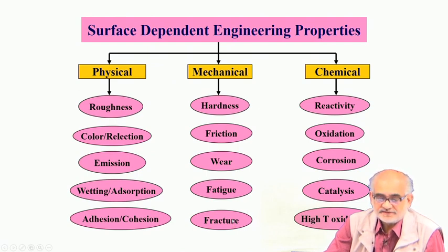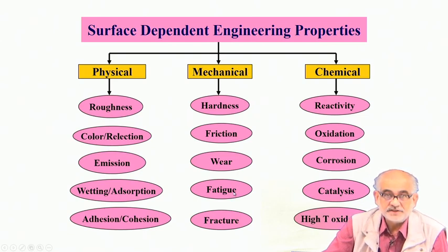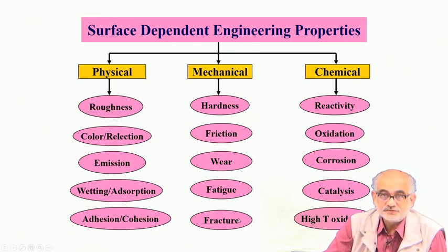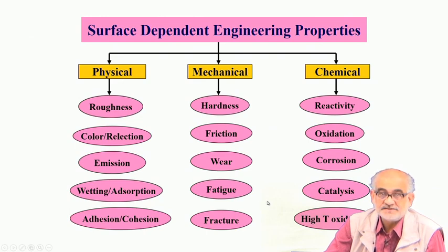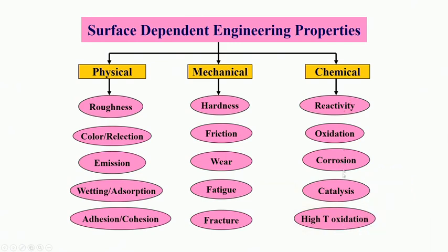I must also qualify that fracture and fatigue are not entirely surface dependent properties, but the failure from these two classes essentially initiate at the surface. So in order to improve upon the fatigue or fracture characteristics, one does take care of the surfaces. Similarly, chemical properties, namely the reactivity, oxidation, corrosion, catalysis, high temperature oxidation, all these properties are essentially surface dependent properties.